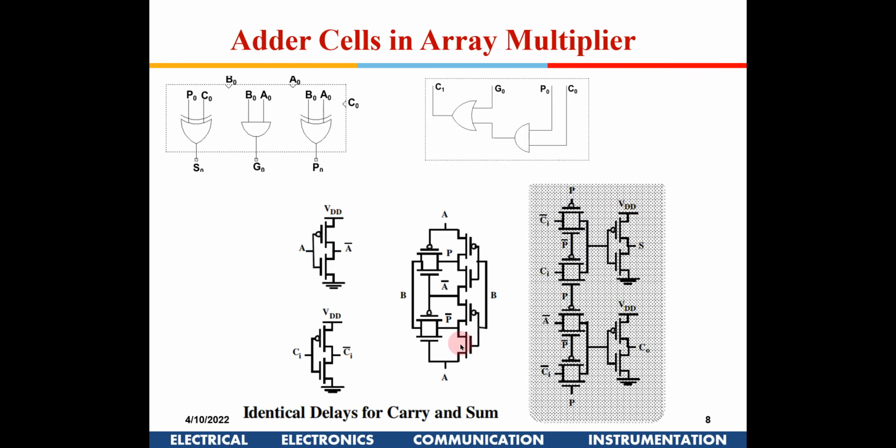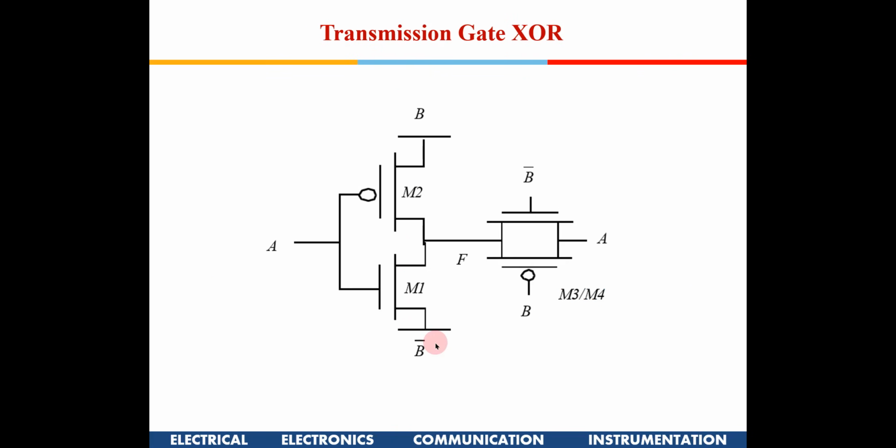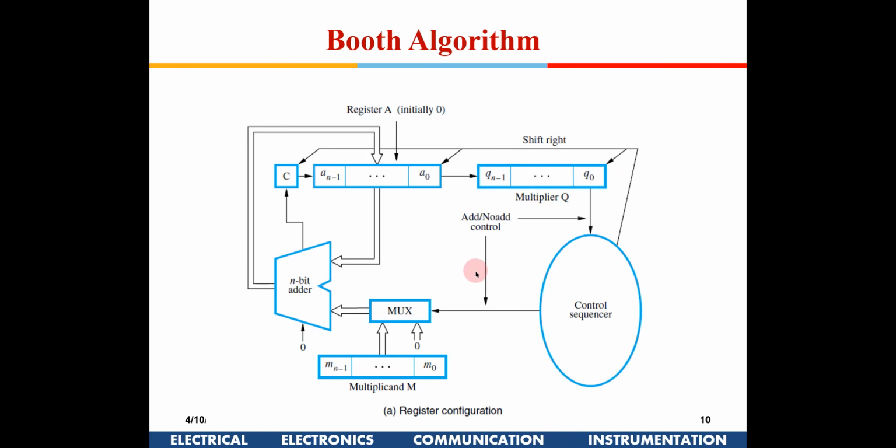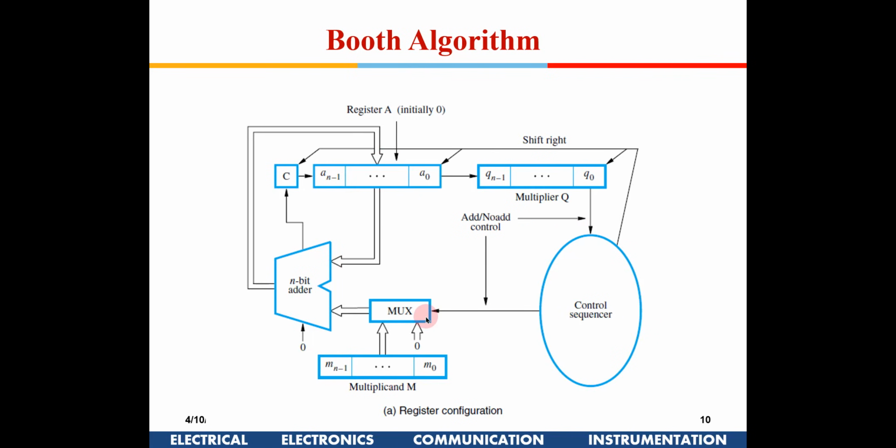Whereas here it is only the propagation delay of the blocks. Only the area and power will be more. But now with clocks operating in gigahertz, even 64 clock cycles is an okay option, considering that the total hardware requirement and the power requirement is very less out here, right?